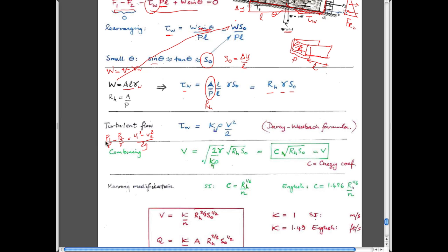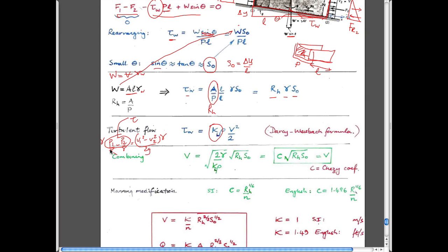You have something which is a pressure change, and of course if the pressure changes from some magnitude upstream to some magnitude downstream, that has to be countered by some shear stress on the side of the pipe. And so you can think of this pressure change here as basically being a shear stress that's applied. This expression merely links a magnitude of pressure to a velocity through an assumed loss coefficient. If you multiply both sides by gamma, this and this go out. Gamma is equal to rho g, and so the g's go out, and you end up with a density in here. So that's kind of where it comes from.